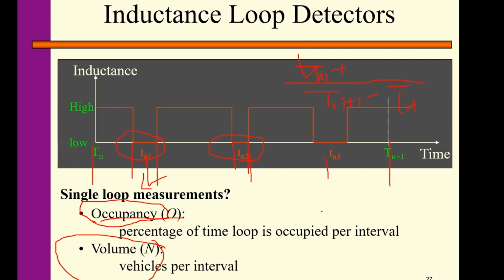And there's a problem. Sometimes we want vehicle speed, and we want vehicle length. This cannot be measured by the single loop detector, so we have to convert those measurements to speed and vehicle length. This is more desirable for traffic management.